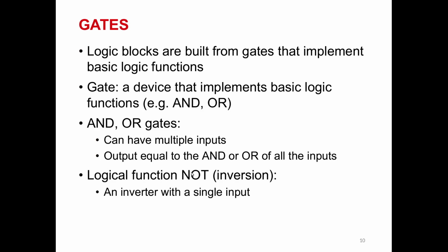Here AND, OR, and NOT are the 3 basic logic functions that we will use in our implementation of any digital device. For AND and OR gates, you will have multiple inputs, at least 2, and you can have 3 or 4, 5, but in real hardware you should have maximum 3 inputs for AND and OR gates, but on paper or in our exercise you can have multiple input AND and OR gates.